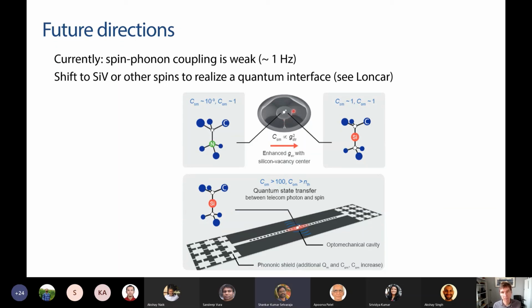So you mentioned that the highest Q you are getting is for a TE mode, but I would expect the highest Q for a TM mode for a disk, because surface roughness contributes to TE edges, but the TM mode will not suffer because the top layer and the bottom layer don't see the hard isotropic edge, right? Or anisotropic.